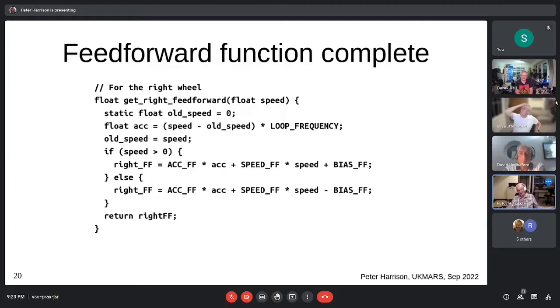You could, if you wanted to, put it on a drag race track, put 2 volts into it, and set up 2 timing gates a couple of meters down the drag race track and measure the time between the gates. That would be perfectly reasonable. Remember, it only took 800 milliseconds, 500 milliseconds to get up to its terminal velocity. If it was a very heavy robot and had a very low gear ratio, it might take longer. But the point is, all you need to know is that terminal velocity against voltage, and it doesn't matter how you do it.